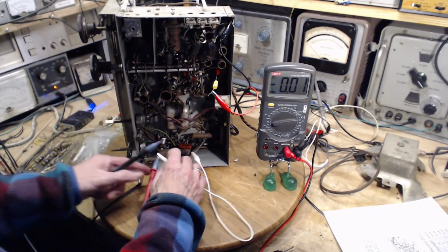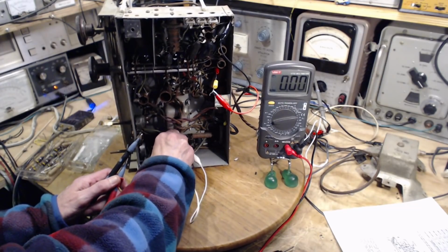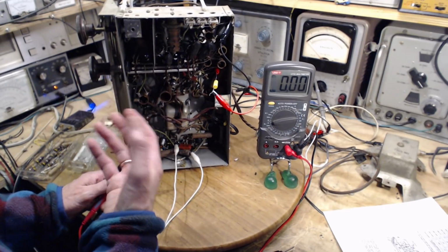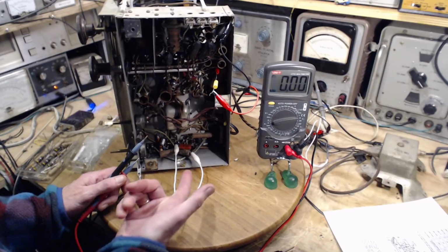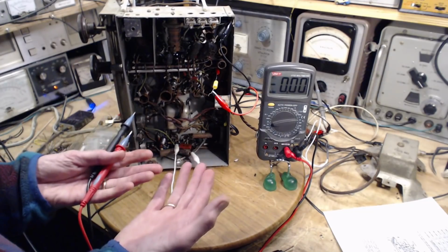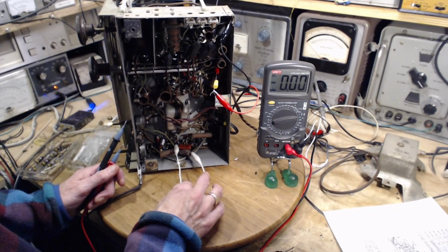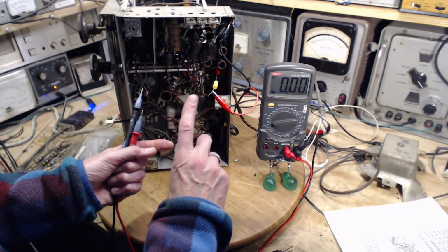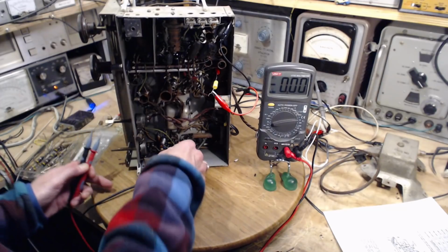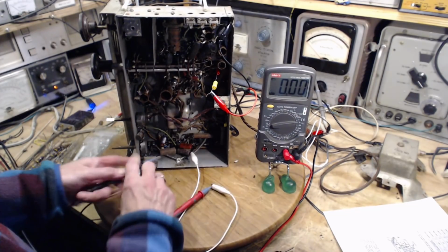I'm going to put a short on the capacitor. Okay, I'll give that a moment. So what I believe is happening now is I'm draining down the charge that's in the capacitor, but the capacitor is working like a battery. So it's got some EMF in it itself. So this will bring it down to a certain point. Take the short off, put the voltmeter on, and we should see the voltage going up, and that tells me the capacitor itself is generating voltage. Believe it or not. Here we go. Fairly quick on this.